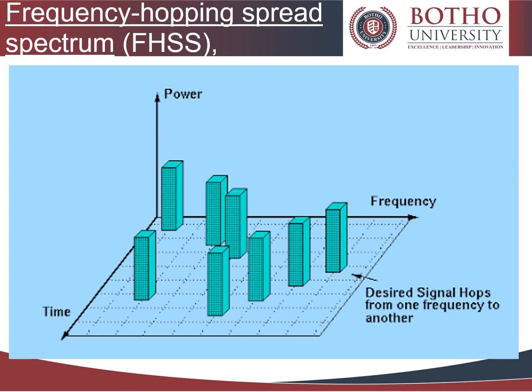Now, FHSS is a method of transmitting radio signals by rapidly changing the carrier frequency among many distinct frequencies, occupying a large spectral band. The changes are controlled by a code known to both transmitter and receiver. The frequency hopping spread spectrum technique uses m different carrier frequencies that are modulated by the source signal.